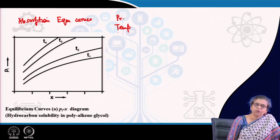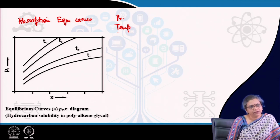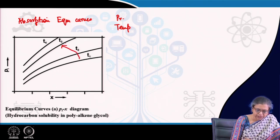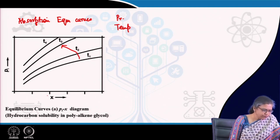So, for most of the absorption cases, they are accompanied by release of heat, or in other words they are exothermic. Therefore, for most of the cases we find that as we increase the temperature, the curve becomes more and more steeper and the solubility of the gas decreases with increase in temperature.